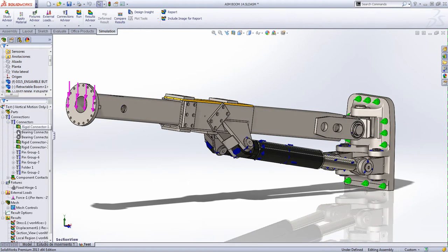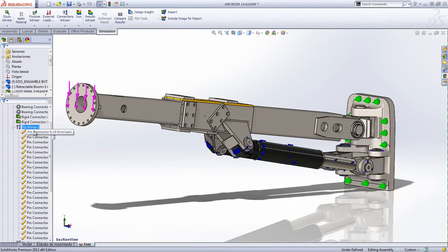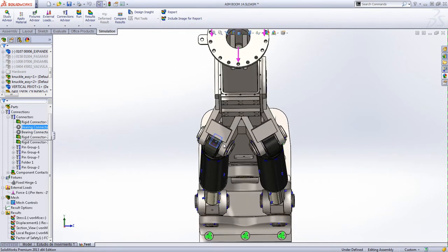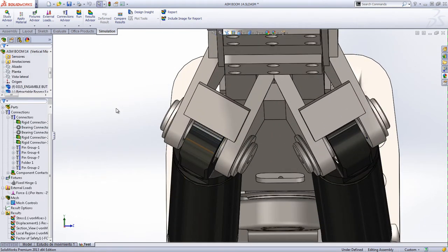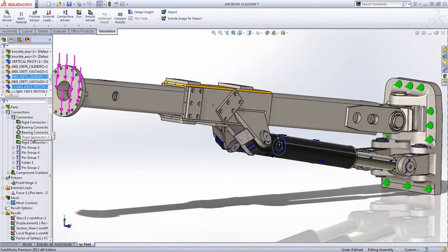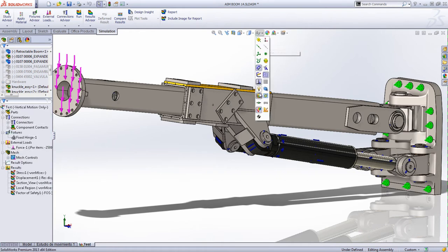We can represent bolt and pin connections to simplify part connectivity and easily get joint loads for sizing. Bushings can also be incorporated to account for compliance in joints if desired, or used as rigid connections as well. Fixed connectors are used to represent the hydraulic pressure holding the cylinders in place so as to determine the resulting loads and stresses in specific configurations. The automatic bonded contact detection simplifies model setup when dealing with lots of parts and complex geometry.